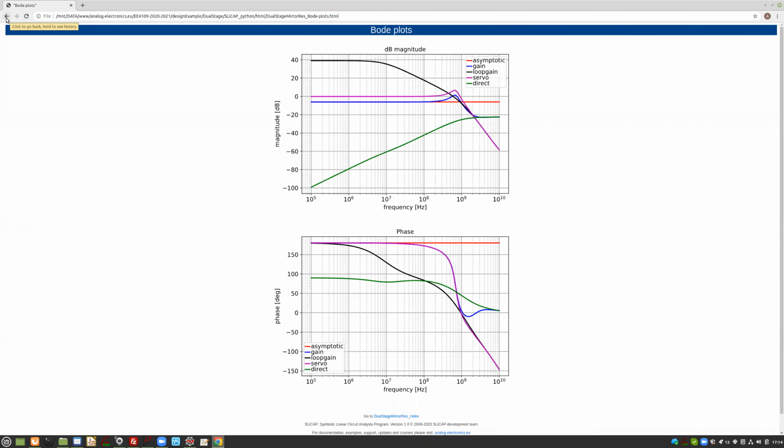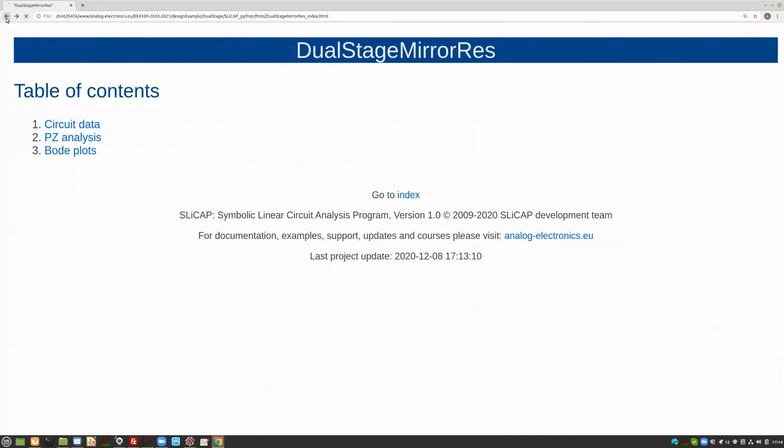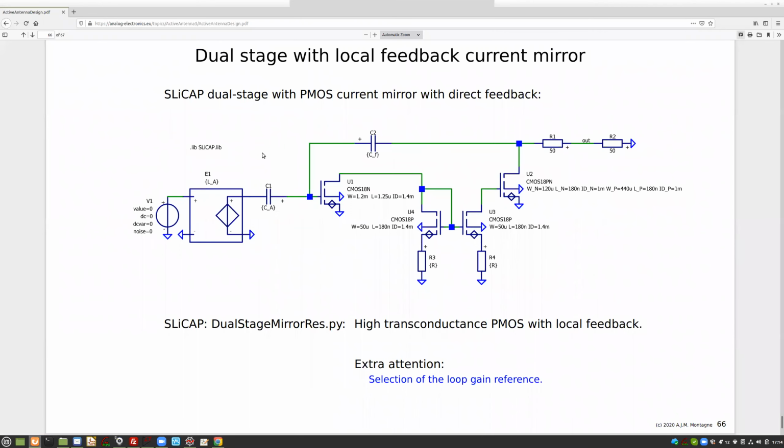For now, the conclusion is that the design of a solution like this, in which we have two CS stages, one is like a class AB output stage, and the other is a single CS input stage, seems feasible from the point of noise, drive capability, and bandwidth.